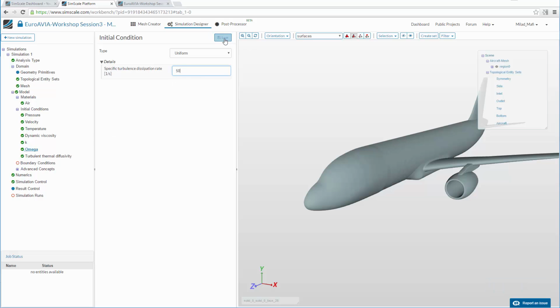And this is important to understand. Basically, K and omega are calculated for the whole flow field. Only for the inlet we know K and omega because we can calculate it. There are several formulas out there you can use. If you're interested in this, I can post them also in the forum.